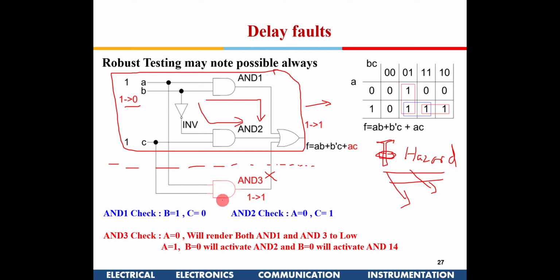In many circuits, but these kind of redundant circuits are a nightmare for the test engineer, right? Because once you insert these redundant circuits, those test vectors and those faults may not be detected at all, and when we run the algorithm, since that test vector is not coming up, the algorithm will keep running, generating many test vectors randomly, trying to fix that. We'll see when we learn about the algorithms. The algorithm will take a lot of time, because it won't know it is redundant, right?